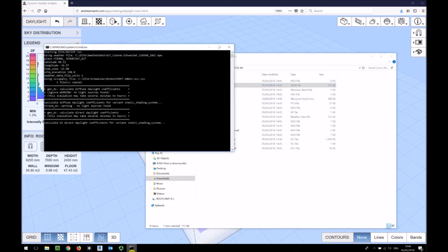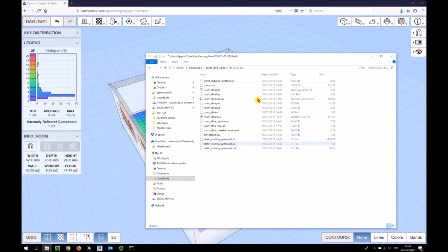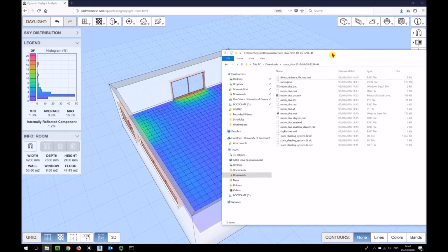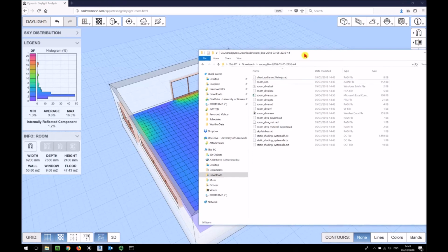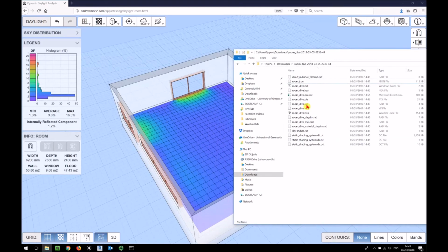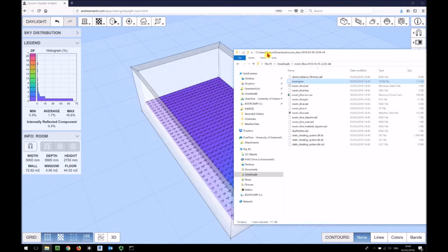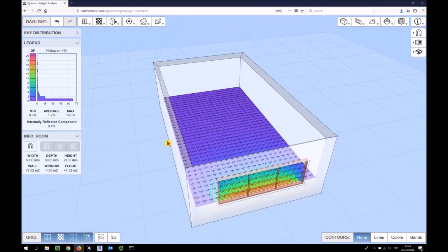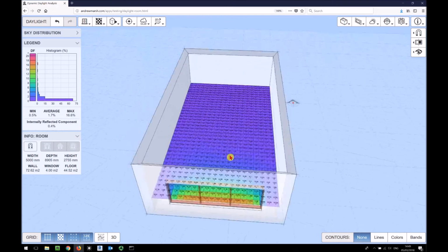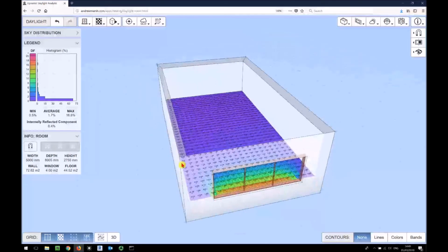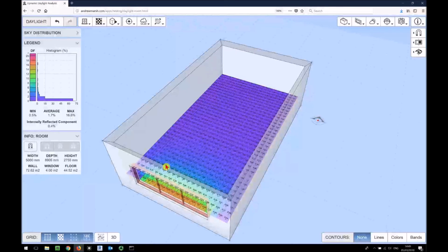So in the next few seconds, that should be in. While we're waiting for the results to finish, I will have this Windows Explorer there on the side and drag the JSON file, so left click on it and then drag it inside the model. As I do this, you will notice that the previous model with all the geometry, all the settings of it, reflectances and so on, has just loaded. So one good thing whenever you export is that automatically a copy of your model with all relevant settings is saved. So you can always bring it back.